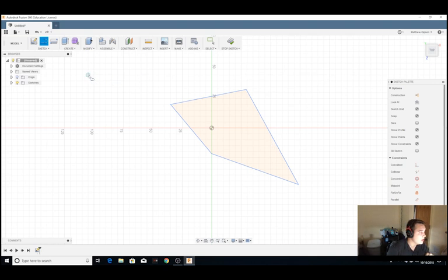What you can do next, if you want something more specific, not drawing freehand or eyeballing the distance: if you want a specific length because you're going to import it to a 3D printer or turn it into an engineering model, then you click at your starting point, which you can even pick through dimensioning. Then you look here and see how the millimeters number is highlighted blue. That means that if I go over to my keyboard and decide I want this 45 millimeters long, and I hit enter, boom. At whatever angle my cursor was at, it gives me the 45 millimeters.